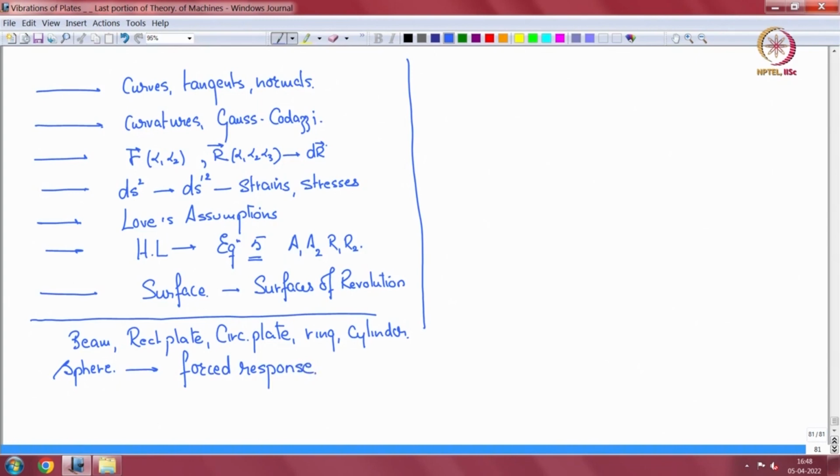In order to do that, our approach is we will need the resonance frequencies and the mode shapes. So we are going to use the modal summation approach. Once you have the mode shapes, you can find the resonances. Once these two important modal parameters are known, we can find the forced response.